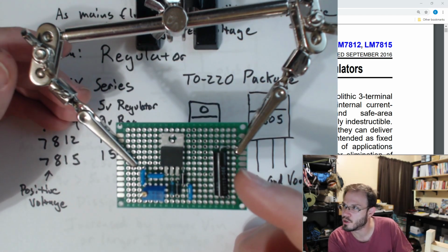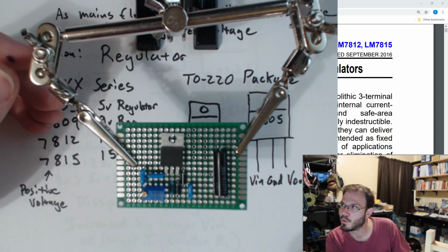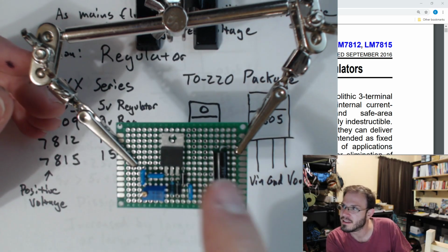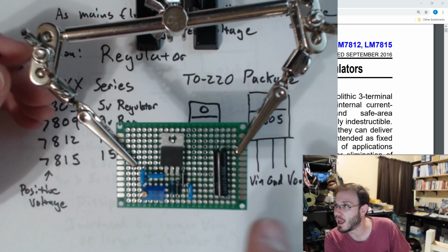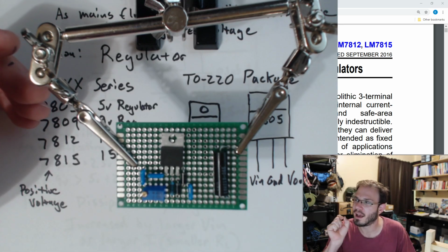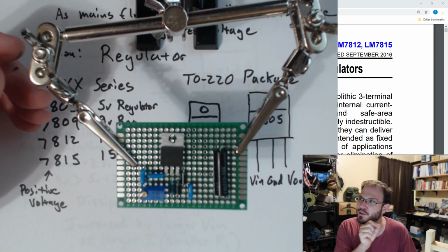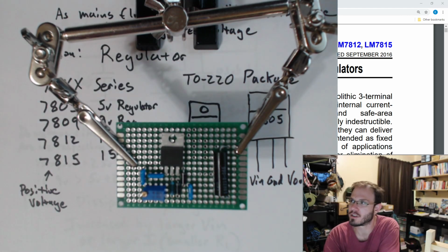This is actually a precision resistor. The resistors you're used to seeing are those blue ones, the 1%. This is actually a 0.01% tolerance resistor. So this guy is 100 times more accurate to 1K than your blue 1K standard resistors are.